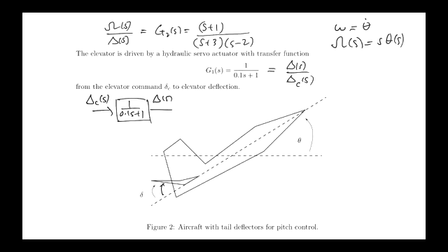So it's got a time constant of 0.1 seconds, right? So after 0.5 seconds, the transient part of the response due to the dynamics here will die away and you'll just get the steady state response, okay? If you put a step command in, it takes 0.5 seconds to get the corresponding step out. Okay, the DC gain is 1 on 1, right? So the size of the thing you get out after 0.5 seconds will be the same as the size of the thing that you put in.